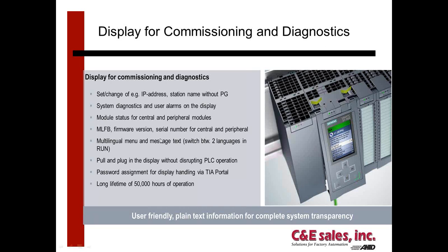You can pull firmware numbers. This set menu can actually be multilingual. You can pull and plug this display without interrupting the PLC, and eventually we will be able to remote mount this display on a panel, so it won't be right on the front of the PLC if you would like to remote mount it.